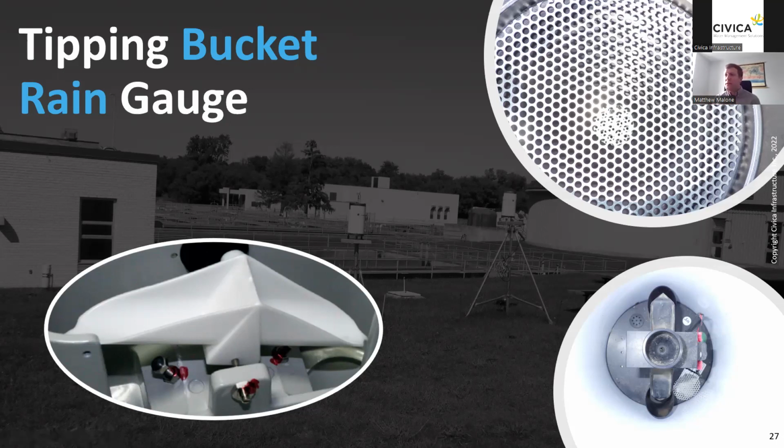So this is typically how we measure rainfall. Most of the tipping buckets we use are measuring on 1/4 of a millimeter, so 0.25 millimeters. Every time 0.25 millimeters of rainfall comes and fills the bucket, it tips, and then fills up the other side and keeps going until the rainfall stops. So this is your typical tipping bucket rain gauge. Pretty simple technology, but very accurate, at least for the purposes that we're using them for.